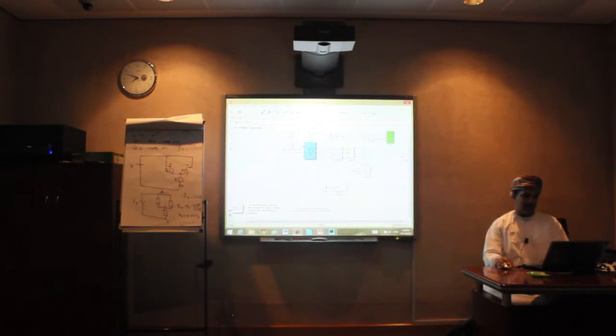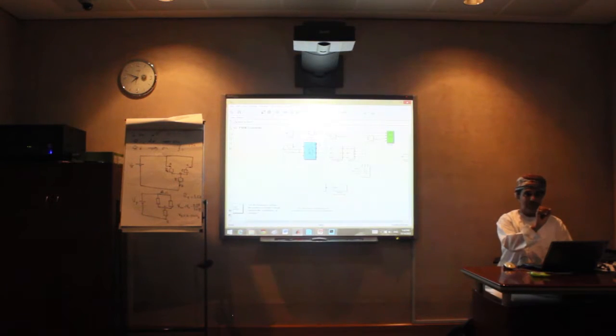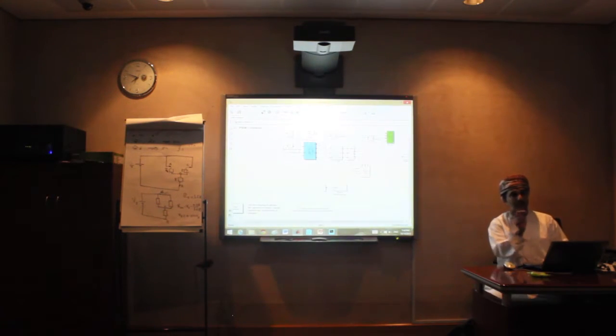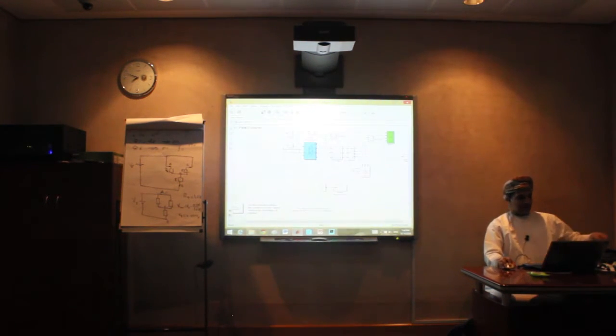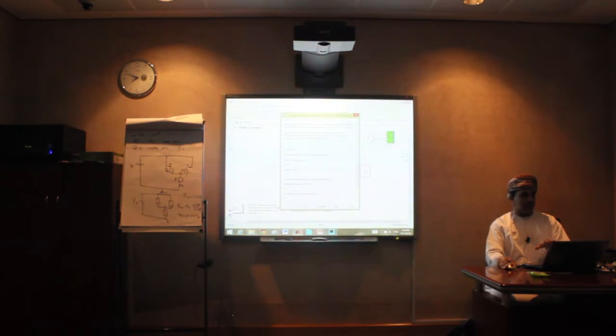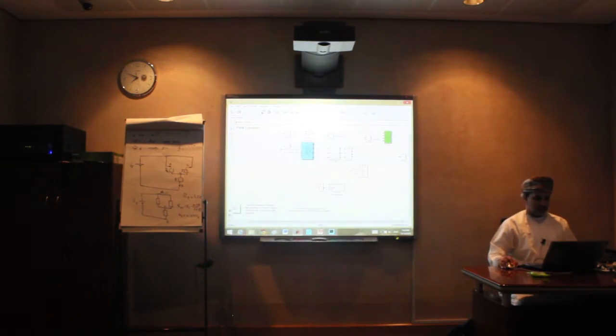And here you need to send 6 signals, right, through that switch. So this one will generate 6 signals to each switch in order to turn it off and turn it on. So exactly, this is the pulse width modulation generator. Here it generates directly the pulse waveform. And I can supply this load with AC. So let's simulate this one and see.